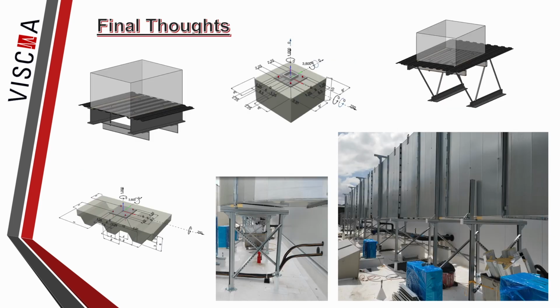Friction forces due to dead load to resist seismic loads are explicitly prohibited by all versions of the IBC code, while the use of friction is not specifically excluded for the resistance to wind loads. Reductions in dead load and vertical wind forces due to code requirements make frictional resistance to wind loads for mechanical equipment impractical. Distributed duct systems, even close to the roof, have too little weight versus frontal area for frictional resistance. Frictional resistance may be possible for small single pipes close to the structure, but ballast loads must be evaluated by the project structural engineer.